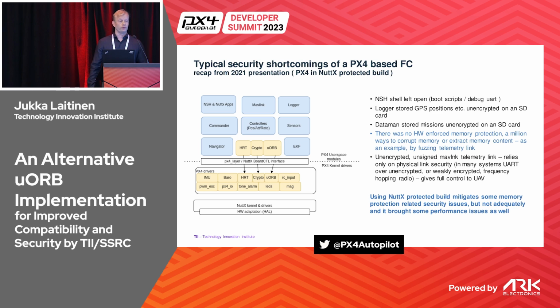And by that we could, for example, isolate some communication protocols such as MAVLink from some security-critical things like cryptography, which we place on the kernel side. This works, and there are examples even upstream in PX4. So it runs on STMs and also our own flight controller hardware.